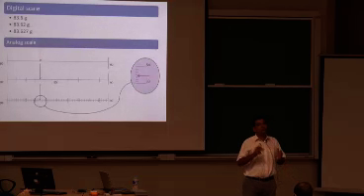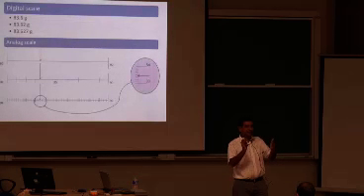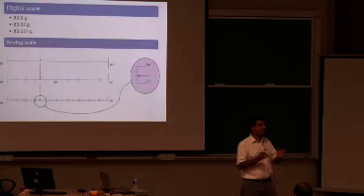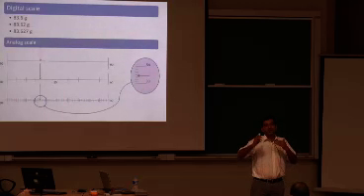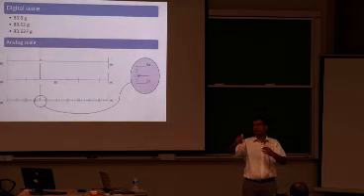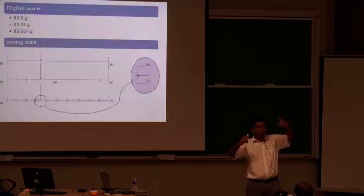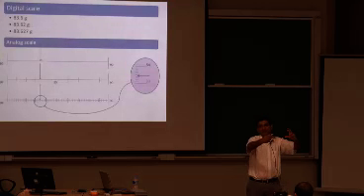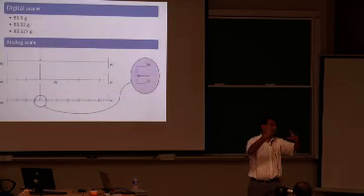You can just look at this pointer and use your judgment to tell that if you divide the gradation between 83.4 and 83.5 into 3 equal parts, it's going to lie in the middle part. So it's close to the center between 83.4 and 83.5.